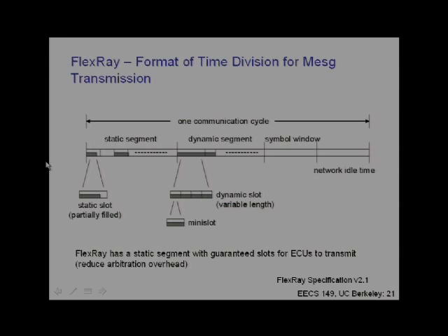So how do you know that this is my slot? It's based on time. So you just measure, using the local clock, the ECU just measures the time to its slot. But how do they know if this is my slot versus something else? Is there priority? It's sort of hard-coded in, right? Yeah. That's what static means. It's basically fixed for the duration of the operation of the system.